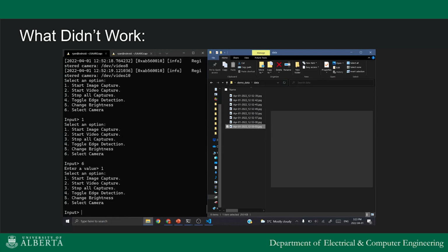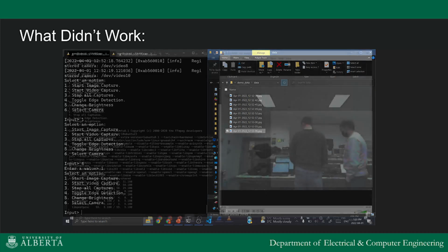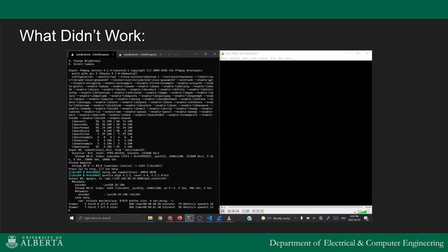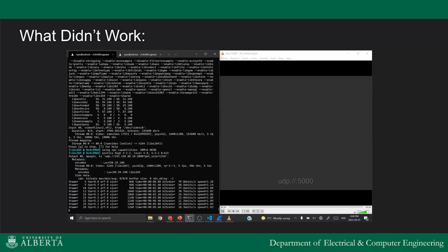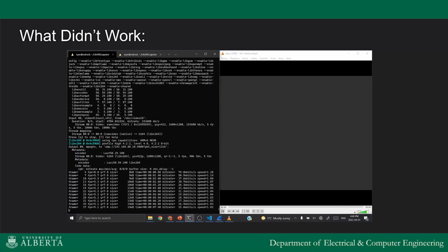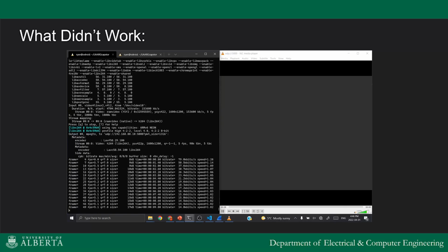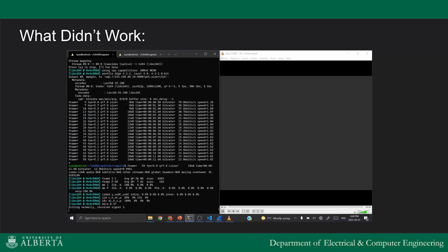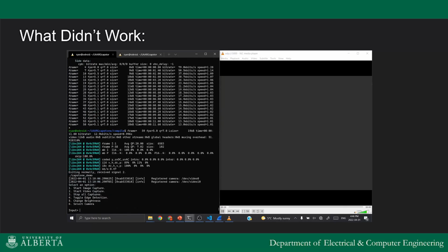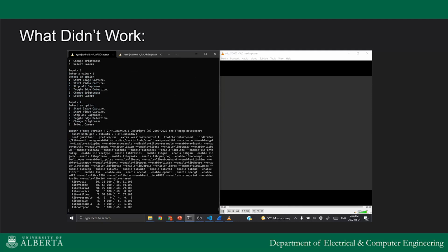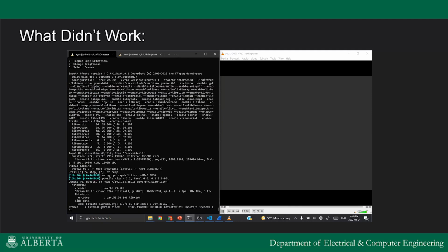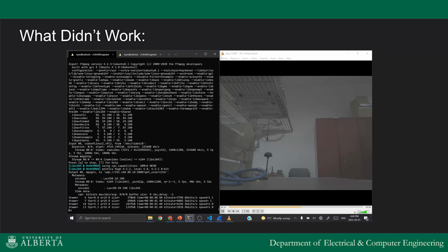During development, we narrowed down this issue to insufficient bandwidth for the USB 2.0 ports. In our case, since our cameras are using USB 2.0, they were not able to use the bandwidth available to the USB 3.0 ports on the Odroid XU4. This limited our bandwidth to a maximum of 480 megabits per second, which must be shared between the two cameras. Note that we don't expect this issue in USB 3.0 ports since they generally have a bandwidth of 5 gigabits per second.